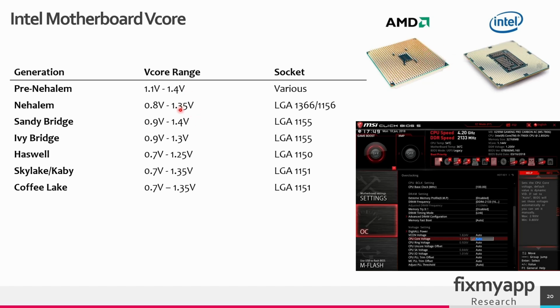The VCore is closely linked to the CPU's operating frequency, also known as the clock speed. A higher VCore allows the CPU to run at higher clock speeds, improving the performance. When users overclock their CPU by increasing its clock speed beyond the manufacturer's rated frequency, they often need to increase the VCore voltage to maintain stability at the higher frequency. Without sufficient VCore, the CPU may become unstable, leading to crashes or errors.